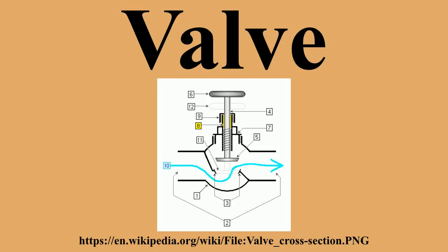Pneumatic actuators and hydraulic actuators need pressurized air or liquid lines to supply the actuator, an inlet line and an outlet line. Pilot valves are valves which are used to control other valves. Pilot valves in the actuator lines control the supply of air or liquid going to the actuators. The fill valve in a toilet water tank is a liquid-level actuated valve. When a high water level is reached, a mechanism shuts the valve which fills the tank. In some valve designs, the pressure of the flow fluid itself or pressure difference of the flow fluid between the ports automatically controls flow through the valve.